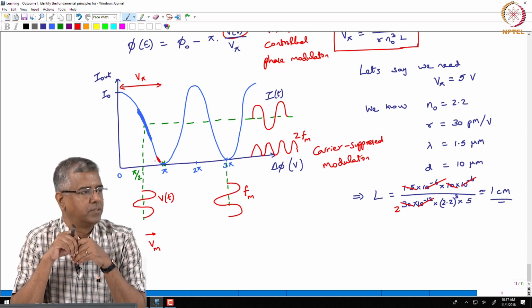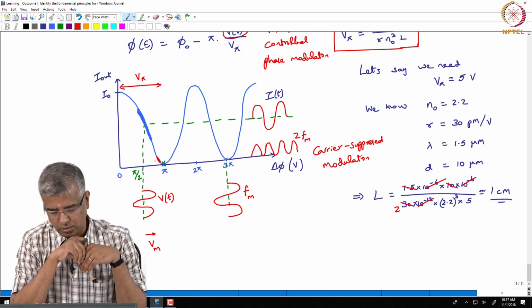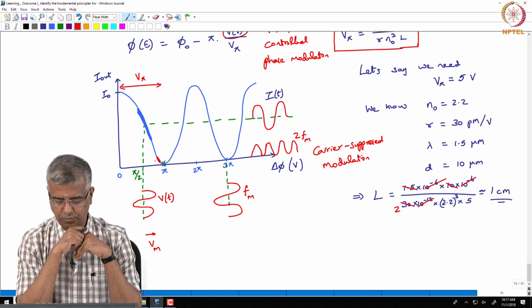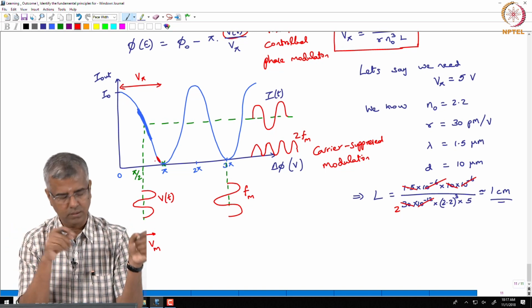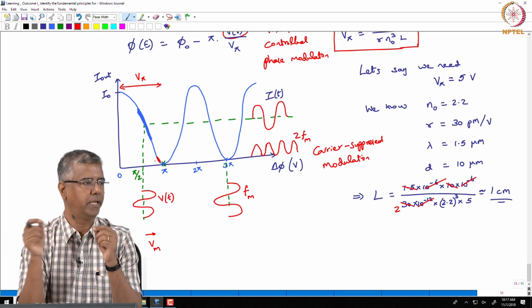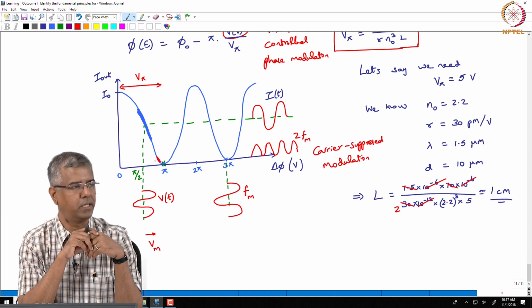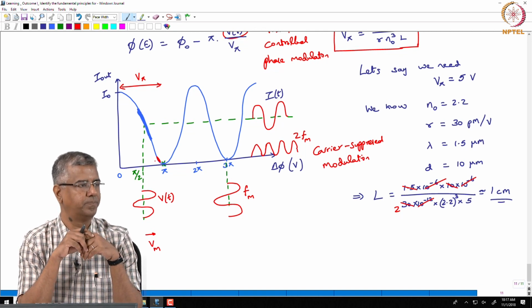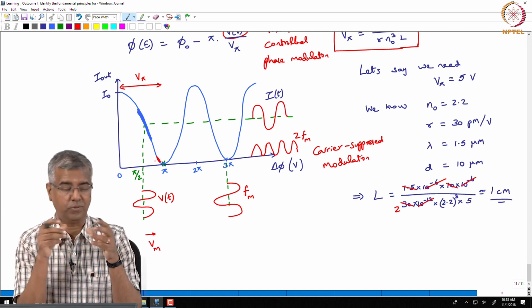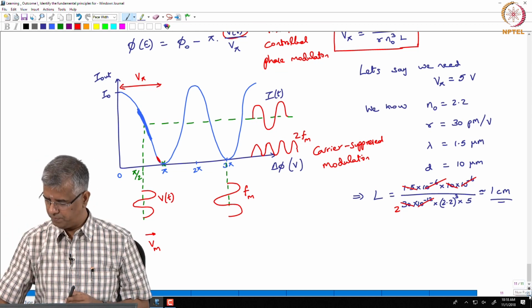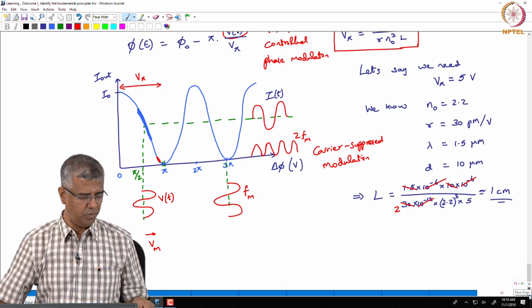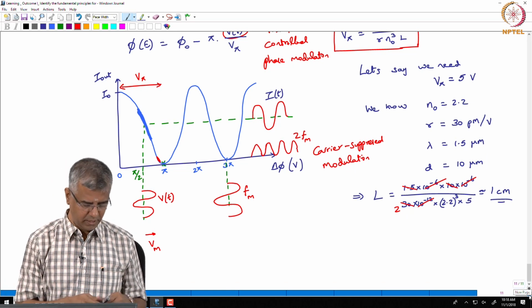Harmonics of that, yes, right. So, you do get whatever frequency you are trying to achieve. And of course, if you are biasing around the null point, it is straddling both sides, in which case you get twice the FM that you have. And of course, you could get harmonics of that also. So, that's so much we want to talk about second order susceptibility.